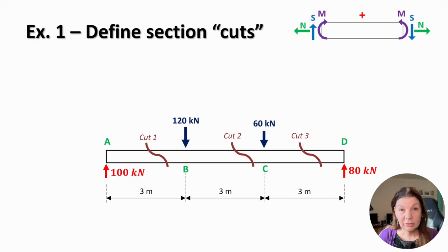We now divide the beam into regions using section cuts. The cuts are placed at points to analyse the results in internal forces when loading changes, in this case before and after the applied point loads. This is important because within each region, the loading remains constant, which allows us to write a single set of equilibrium equations. In this example, we define three regions: from A to the first load, from the first load to the second load, and from the second load to the right support. Within each of these regions, we introduce a variable position and derive expressions for the internal forces.